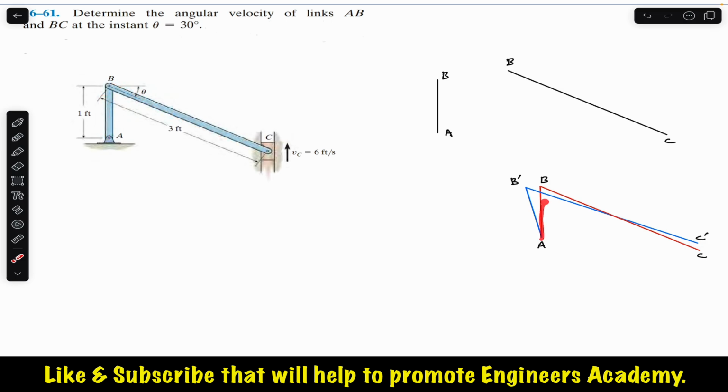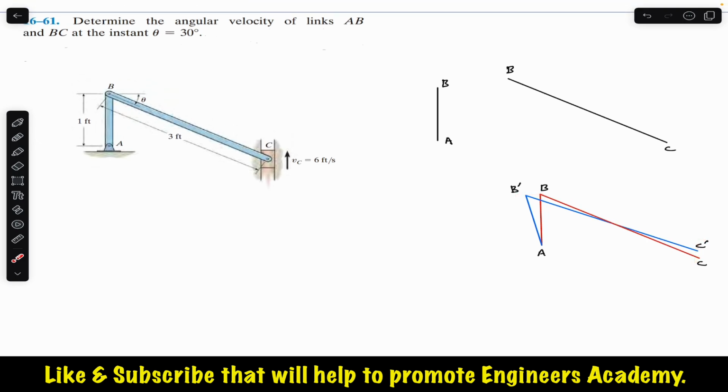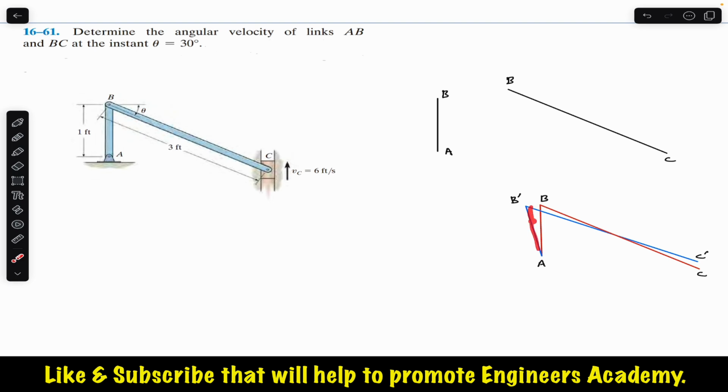So let's say that these two red lines represent links AB and BC, and red represents the initial state. So when this point C goes up, since the block C has a velocity of 6 feet per second in the upward direction, this point B will move towards the left. This means that link AB will have the angular velocity in this direction, that is, in the counterclockwise direction.